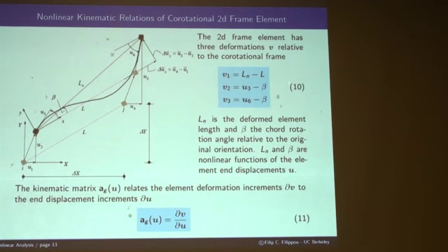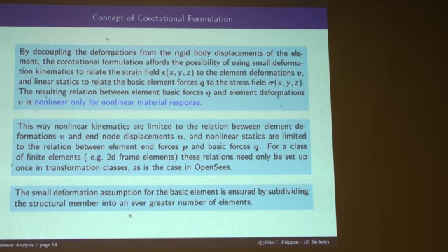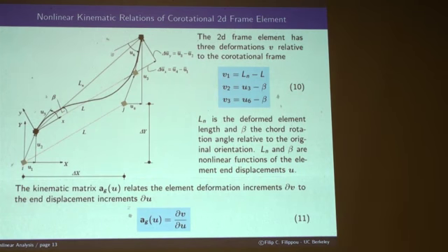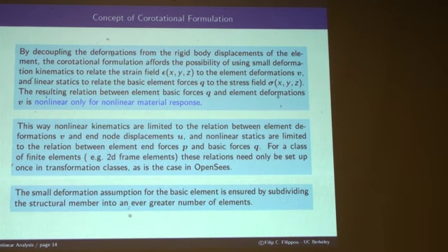While, of course, we are going to use large displacement kinematics to relate the displacements to the deformations, the most interesting part is that the strains inside the element use small deformation kinematics. So the element formulation is very simplified. The continuum problem is simplified immensely. The discrete problem remains nonlinear.